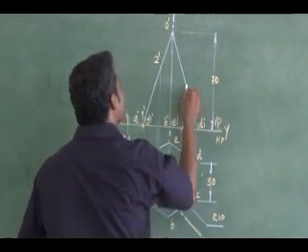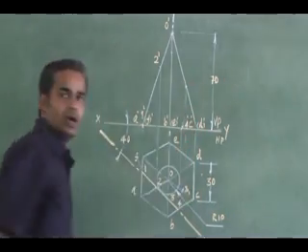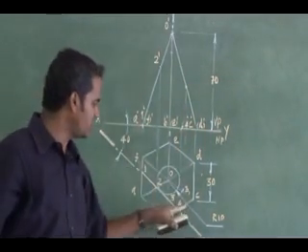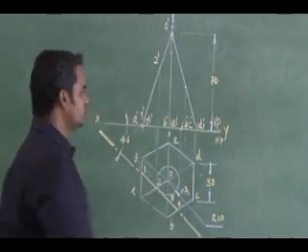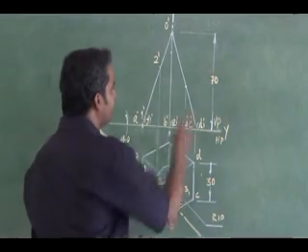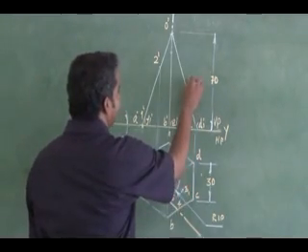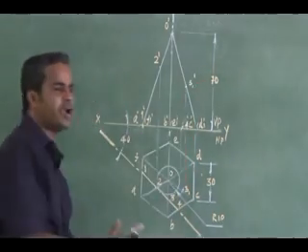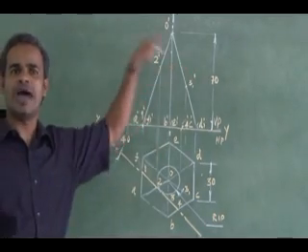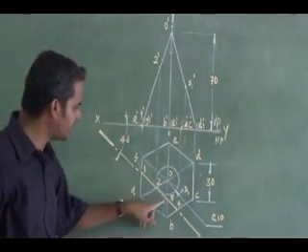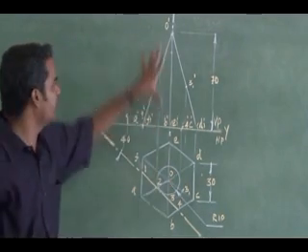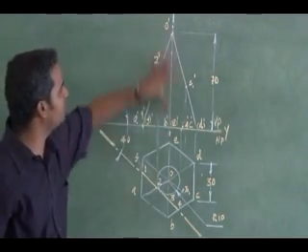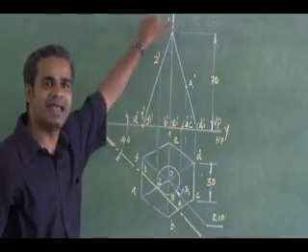This 3, 1 can be projected to the corresponding slantage. What is that slantage? That is OC. It is projected to OC. Here I have in the extreme, that is my 3, 1 dash. So this is not my actual cutting point. Where do I have to mark this cutting point? Actually the cutting point is on OB. The cutting point is on OB. So I have to mark the cutting point in my front view on the OB slantage.